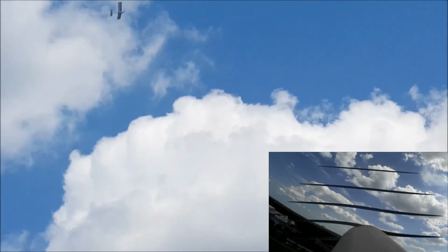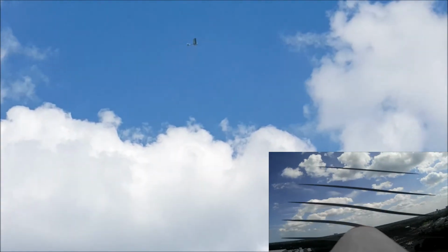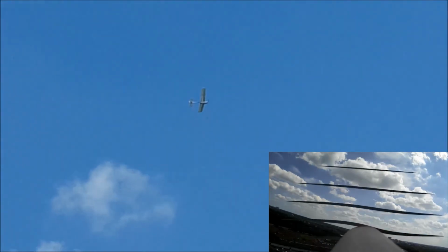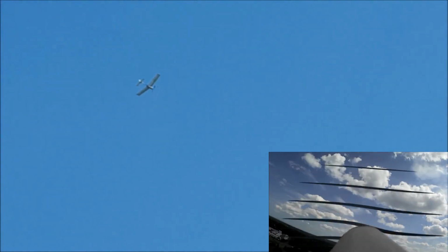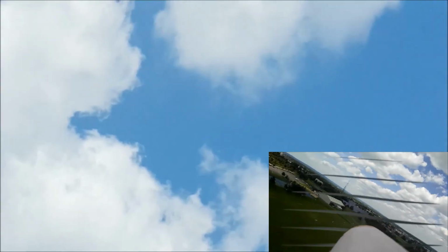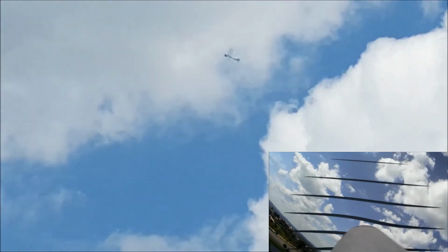What you see here is actually the third test flight of our plane, and this was the first test flight in which we mounted the Mobius action cam on top. This camera, of approximately 2.4 ounces in weight, increased the total weight of the plane from 13.6 ounces to 16 ounces. Because we mounted the camera on the center of gravity of the plane, this increased the stability greatly and allowed the plane to be stable throughout its flight.